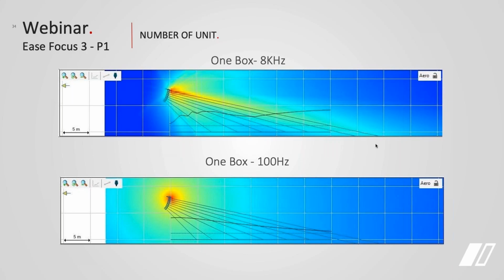That same box at 100 hertz radiates outwards towards the back of the box and the front of the box, more than everywhere else. So if I had all 8 boxes turned on, 100 hertz or around that area tends to sum up greatly. So we tend to lose all of our high frequency range, not because it's not going, but because all of our low mids in the boxes have summed up.